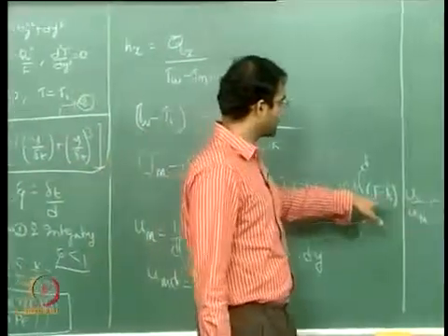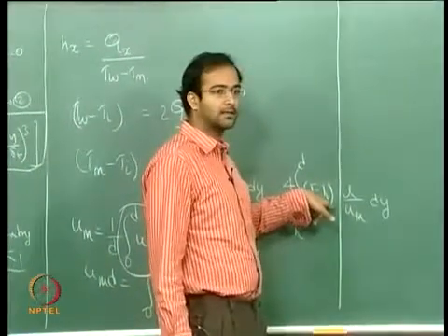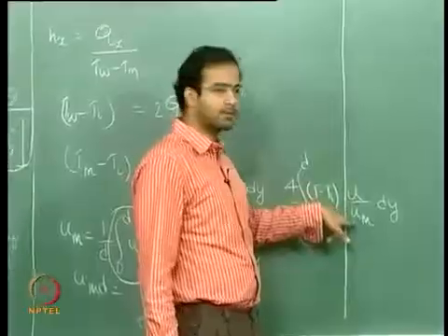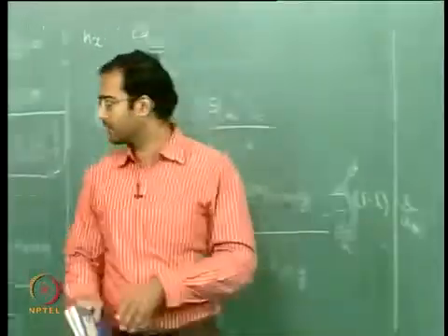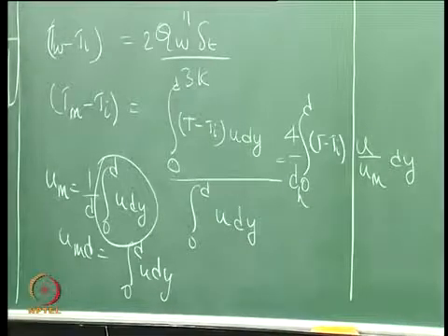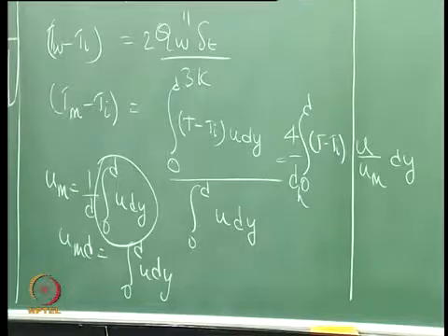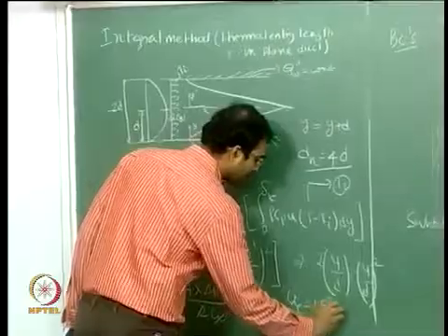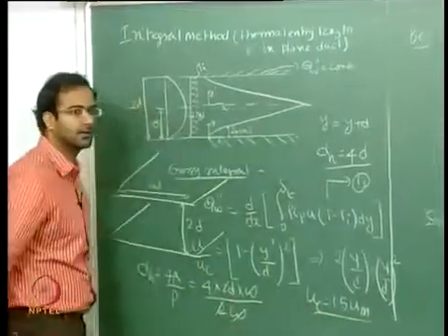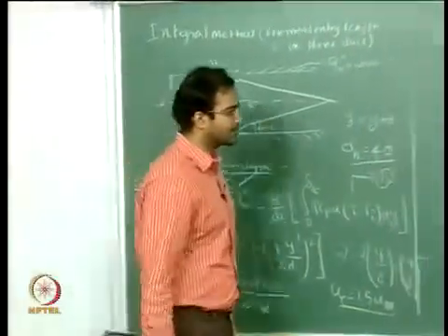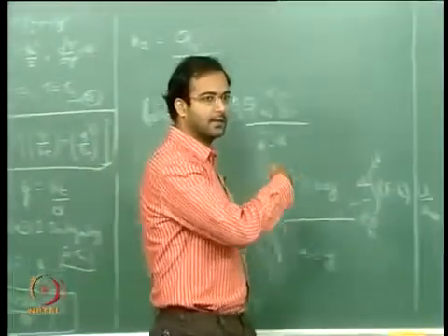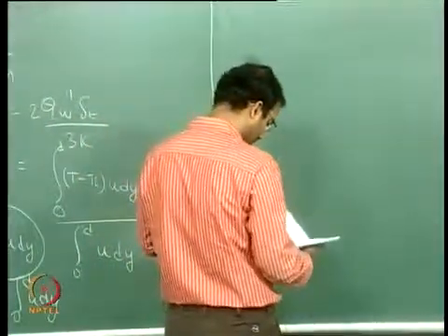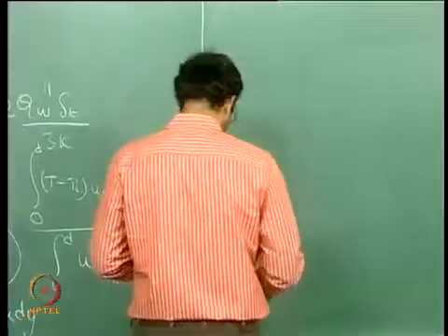So finally this is my relationship for calculating the mean temperature. I simply have to substitute my temperature profile into this. I know my velocity profile u by um, which, in the case of channel flows, again your center line profile is 1.5 times your mean velocity. So this can be substituted and you can integrate and therefore determine the expression for Tm minus Ti.